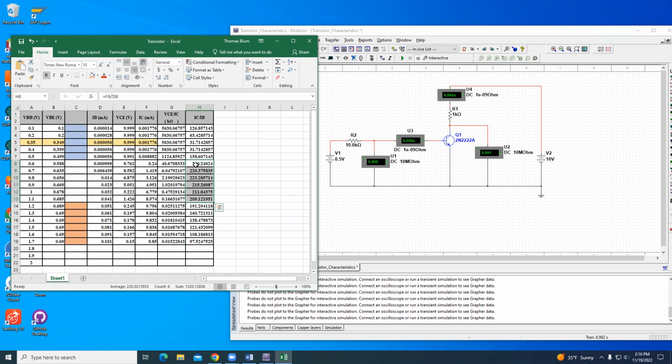So there's a region of amplification: there's an off, there's a transition, there's an on. When you're working in the transition region, you can use it as an amplifier, whereas if you stay out of that region and go from on to off, then you're using it more as a switch, more logically. So that's what I wanted to show you. Thanks for your attention.